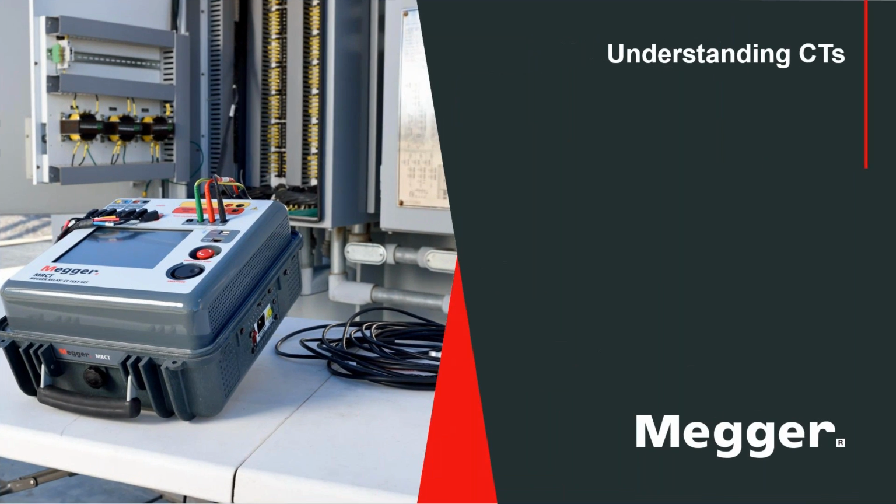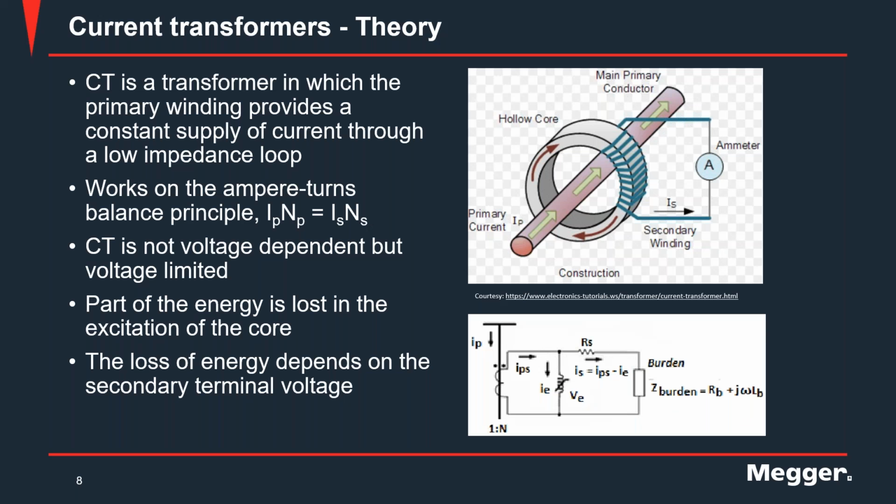Okay, let's get started. So let's talk about what current transformers are. Let's start from the very basics. So a current transformer is a transformer, right? It looks different, but it's essentially a transformer. The way it functions is the CT is wrapped around a primary conductor, and when the current flows through the primary conductor, the field that is present around the conductor, because of the current that flows, is channeled in the core, and because of that, a voltage is induced, but because the secondary is shorted, a current flows instead through that shorted secondary circuit.